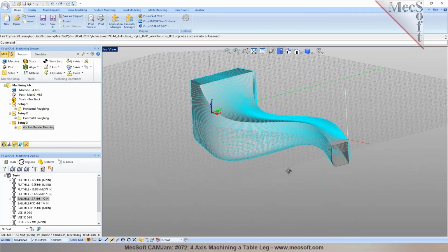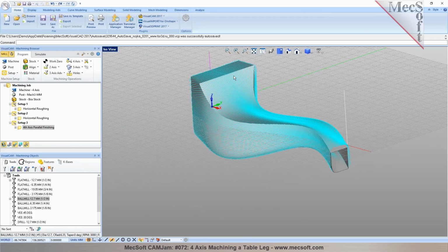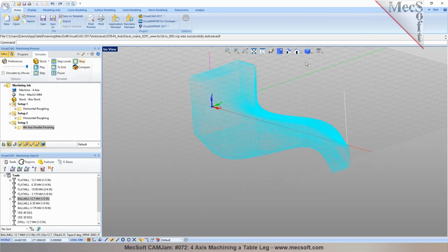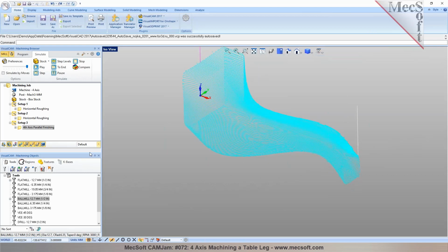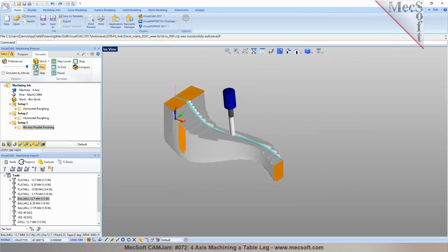The toolpath, what you see that's generated in here, is basically going along the axis, and the tool remains normal to your rotational axis. So when you run a simulation, you'll notice that actually the part rotates, but in the simulation you're noticing that the tool is going around the part. Okay. So what you're performing here is just a cut material simulation. If you perform a machine tool simulation, you will notice that it's the part that actually rotates. Okay. So this would be a continuous 4-axis finishing operation.